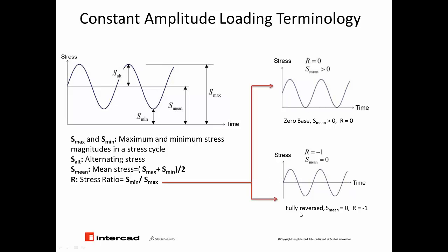And the other type is fully reversed, where you can see the mean stress is sticking to nearly 0 value, peak stress is plus, and minimum stress is a -1. And that is more critical if it's happening in our design studies. That simply means having compressive and tensile loads acting on the component will significantly reduce the life of our design. So mostly we are concerned about this one as a hypothetical stress fluctuation if it's happening.